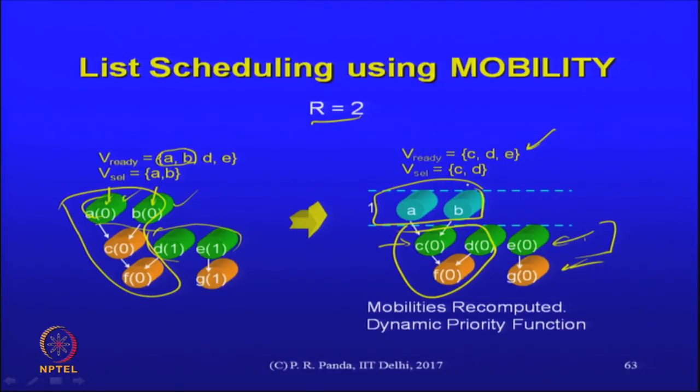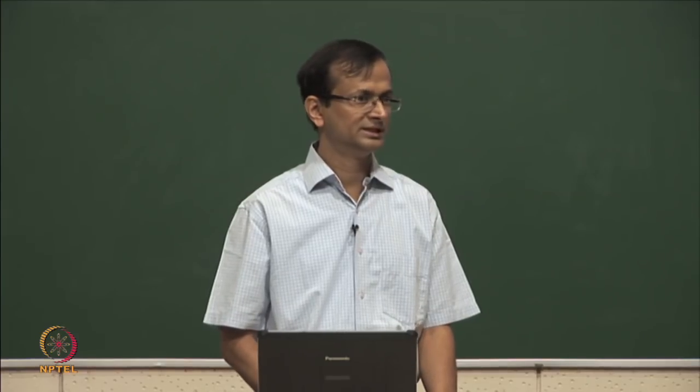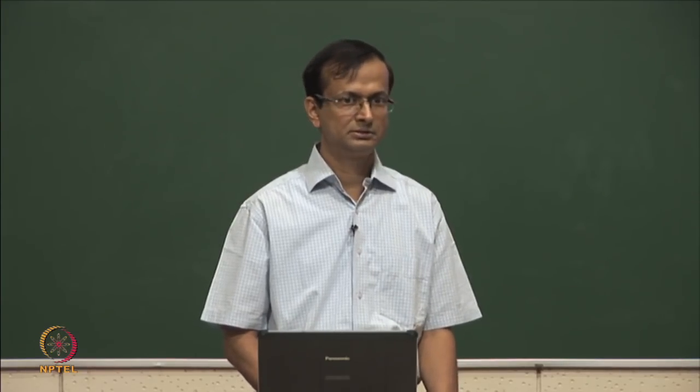But in the interest of time, this strategy does not revisit the decision for a specific node. Under that constraint, once you have taken the decision for some nodes, you might as well forget about those 2 nodes and drop them from the graph. Because of that, everything would change. Now, when you do ASAP and ALAP, a different set of nodes would fall in the critical path.